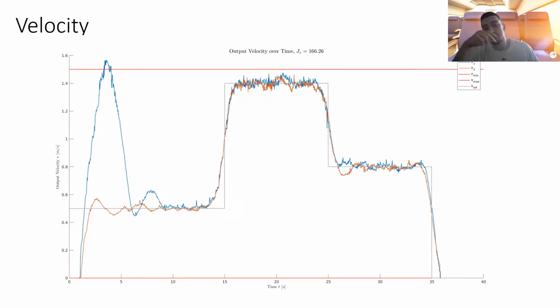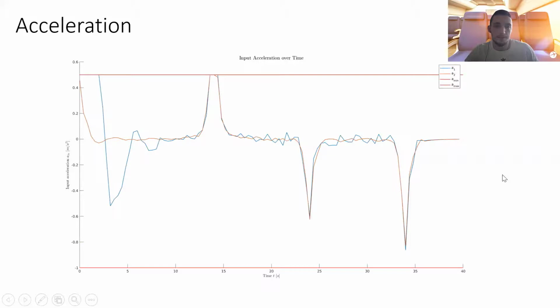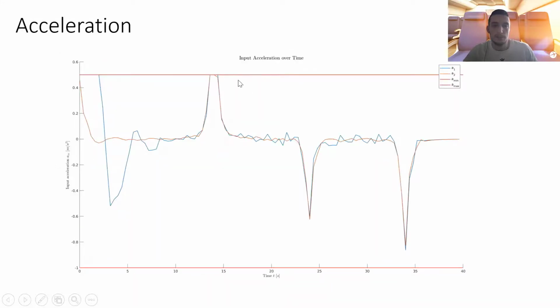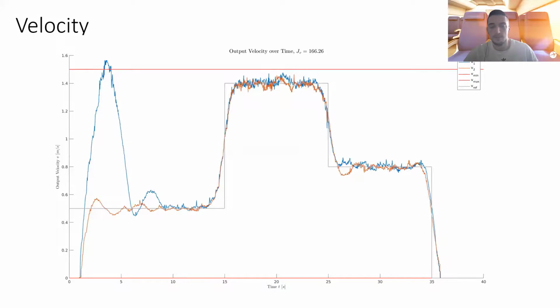Also due to time limits, we couldn't manage to really tune the MPC or make anything great out of it. As you can see here, for the quick tracking, due to vehicle dynamics, we're already at the limit for the acceleration. Maybe you can change this by extending the control horizon a little bit to track earlier, but I guess that's the maximum it can get for reference tracking, at least for velocity.